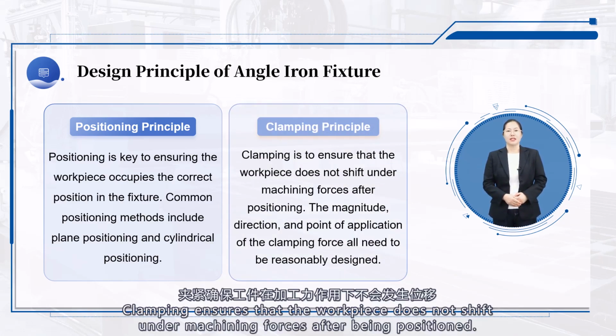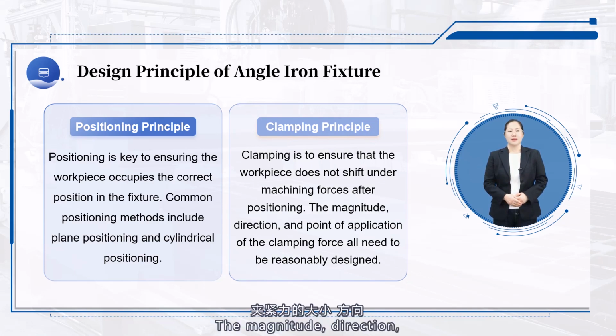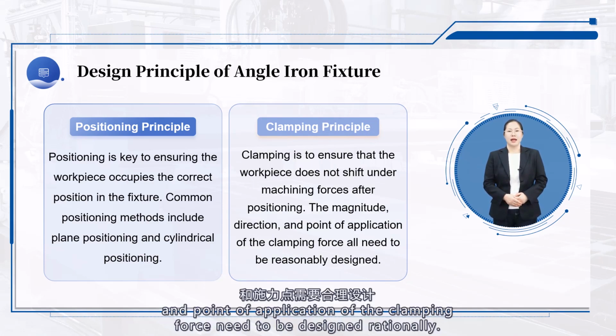Clamping principle. Clamping ensures that the workpiece does not shift under machining forces after being positioned. The magnitude, direction, and point of application of the clamping force need to be designed rationally.